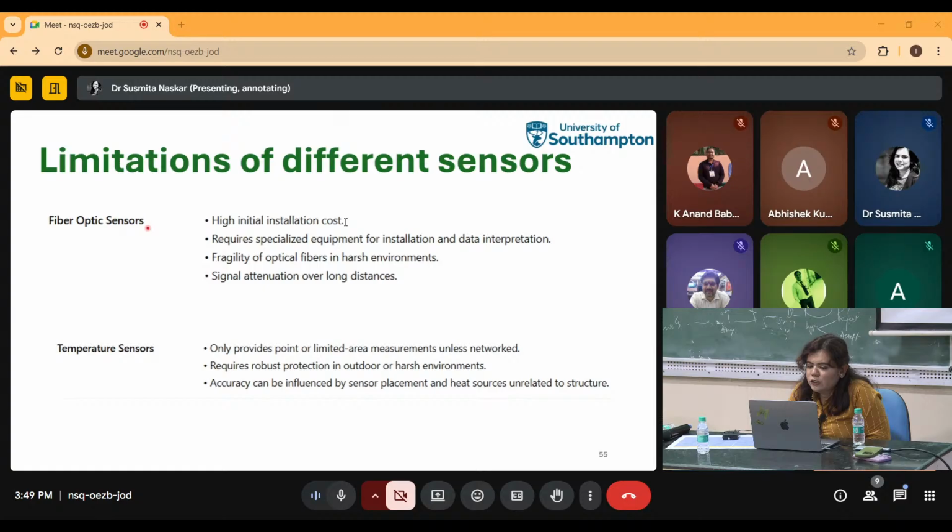And then comes one of the very important factors, which is the automated data acquisition system, and we call it an ADAS. That is nothing but an electronic device designed to automatically read, store and transmit data from various sensors, used mainly in geotechnical, environmental and structural monitoring, right? And what is the purpose and the scope of this ADAS system? The ADAS plays a very key role in monitoring dams. They also serve other critical infrastructure.